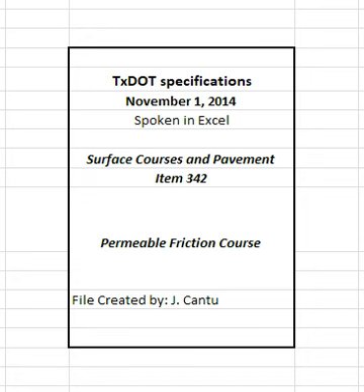4.9.4 Miscellaneous areas. Miscellaneous areas include areas that typically involve significant handwork or discontinuous paving operations such as driveways, mailbox turnouts, crossovers, gores, spot level up areas, and other similar areas. The specified layer thickness is based on the rate of 90 pounds/square yard for each inch of pavement unless another rate is shown on the plans. Miscellaneous areas are not subject to thermal profiles testing.